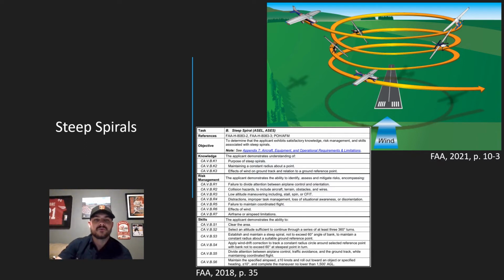Errors for this maneuver are often associated with not clearing the area, inadequate pitch control on entry or rollout, not compensating for wind with bank, poor flight control coordination, ineffective use of trim, inadequate airspeed control, becoming disoriented, performing by reference to flight instruments rather than visual references, not scanning for other traffic during the maneuver, and not completing the turn on the desired heading or reference.